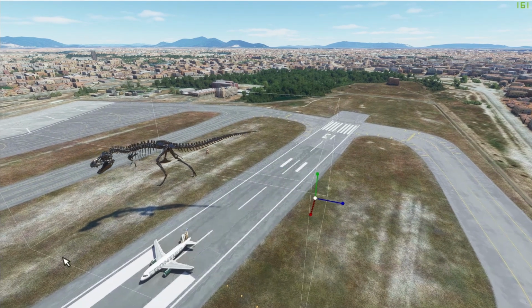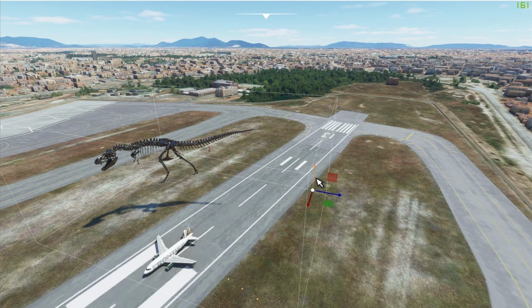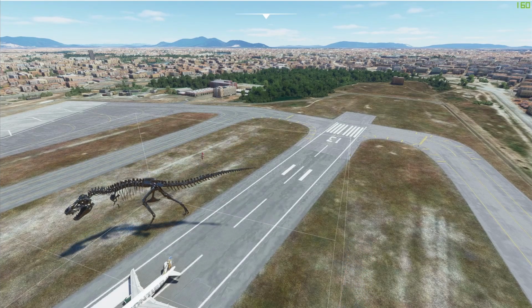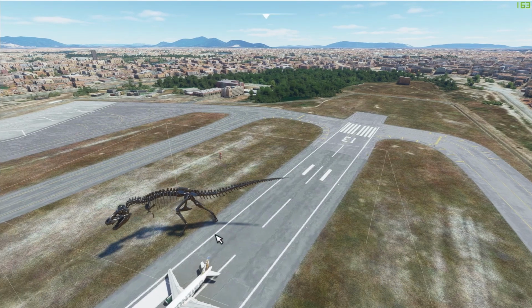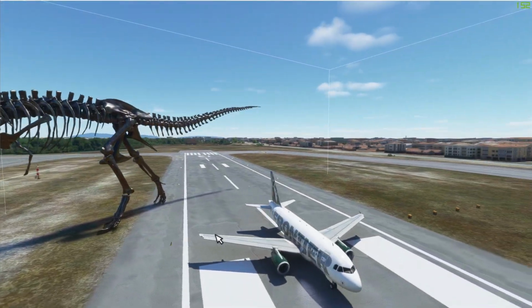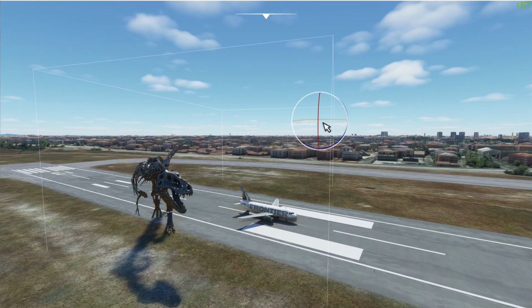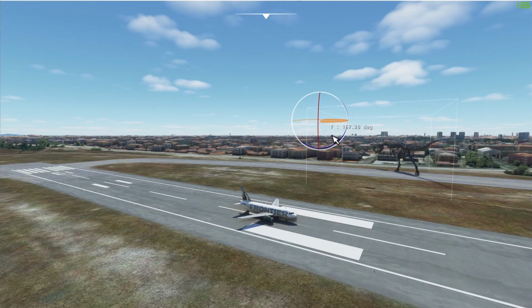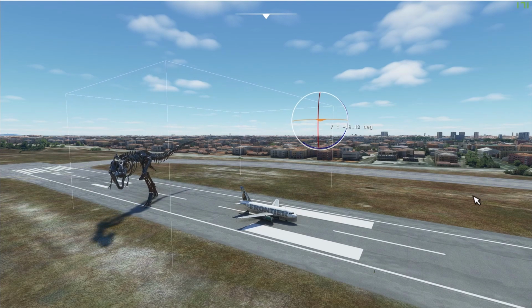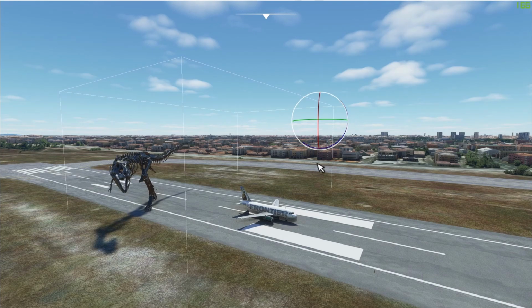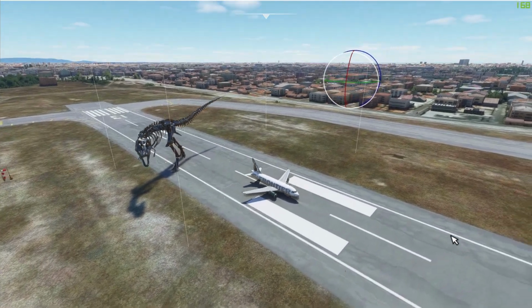There's the T-Rex model. So press the middle mouse button and keep it on the ground. Okay, I think that's good enough. And if you just want to rotate it, press the middle mouse button on this little thing, then select one of the axes and rotate it. Right now the model was not kept at the center of space, that's why it's a little funky, but you can fix that in Blender.